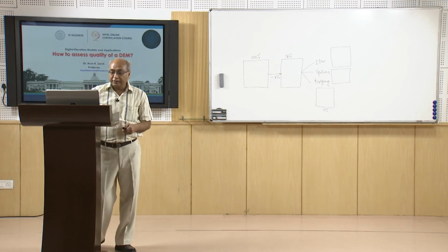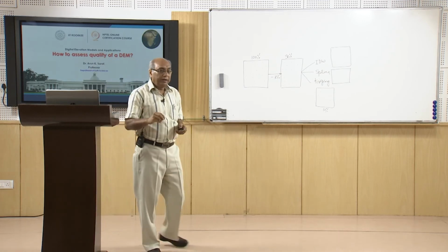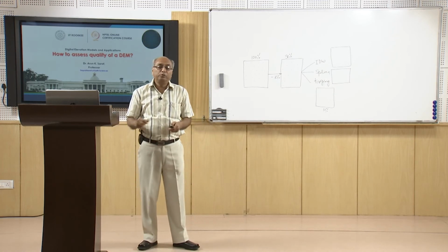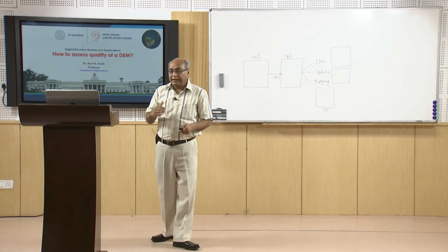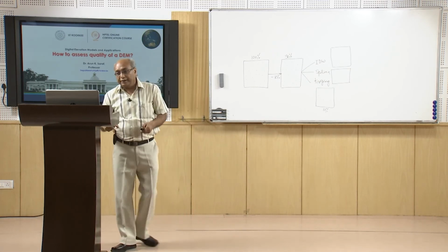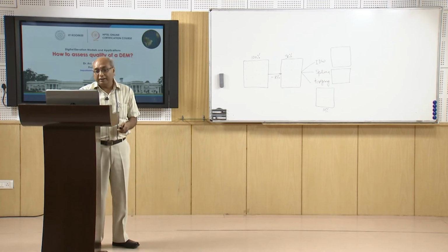So this way we can compare the point heights with corresponding elevation values from the digital elevation model, and can have a feeling about the quality of a digital elevation model. This way we can assess and quantify the errors present, if at all, the inherent errors in these ready-made digital elevation models.